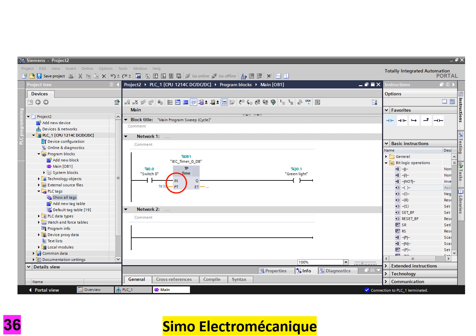TP has 2 inputs and 2 outputs. When logic input IN goes on, the timer starts and output Q immediately switches on, logical 1. The timer runs for the time stored in PT, 3 seconds shown here. Once the timer reaches the value in PT, Q switches off. ET stands for elapsed time. It can be read and used to trigger other events during the pulse time.